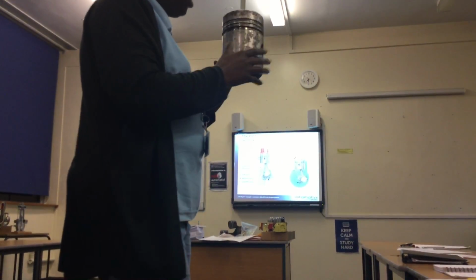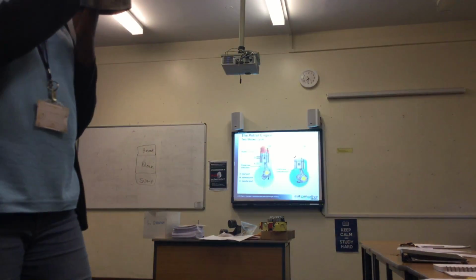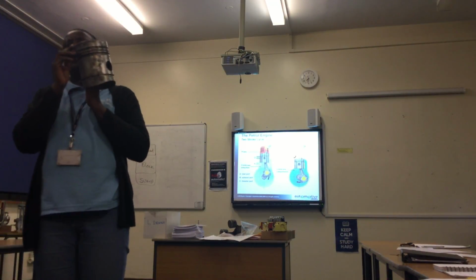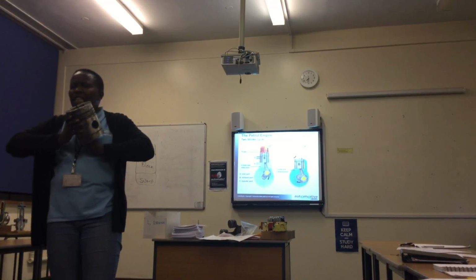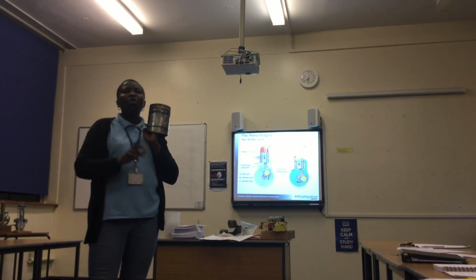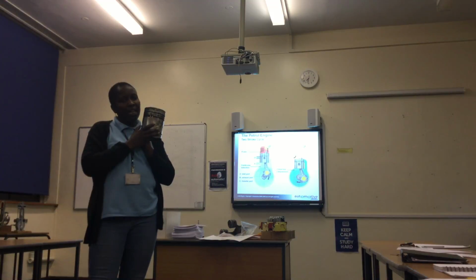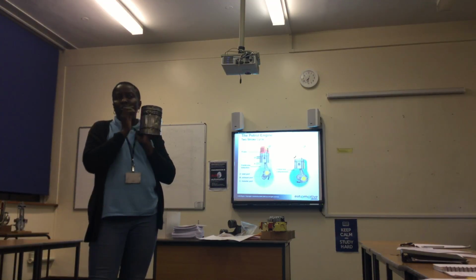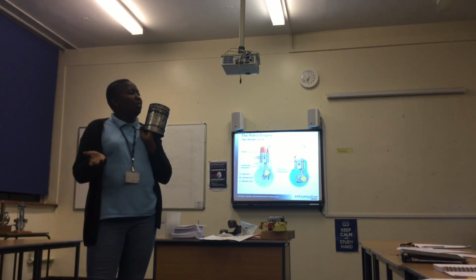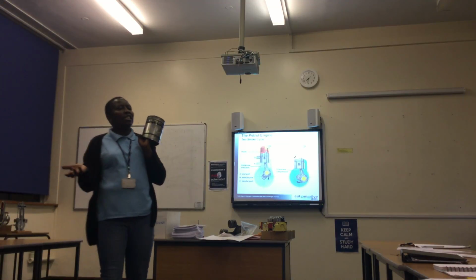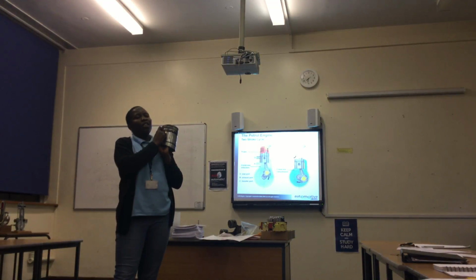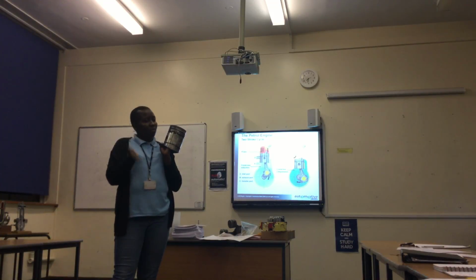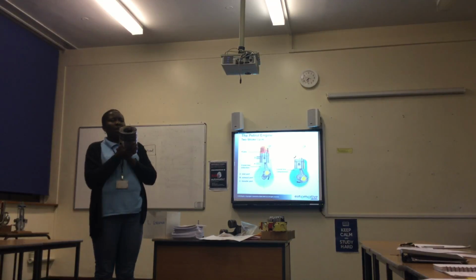As the oil drips through the cylinders, the piston rings will scrape the excess oil. Then the compression rings, remember during compression, they help in sealing the cylinder so that no gas will escape. So compression rings seal the cylinder, prevent gases escaping. Also, oil scraper rings act as oil control or scrape the excess oil.